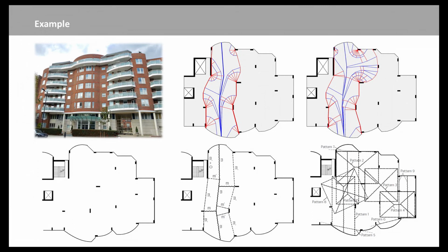Now what I'm going to show is actually a floor plate for an apartment floor that was constructed in central London. This is actually the same apartment floor that was considered in the concrete design guide. What they did in that design guide is they used the hand-based yield-line method. They tried lots of different potential yield-line patterns in order to identify the critical one and design on that basis.